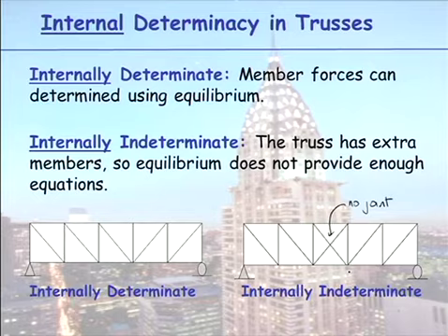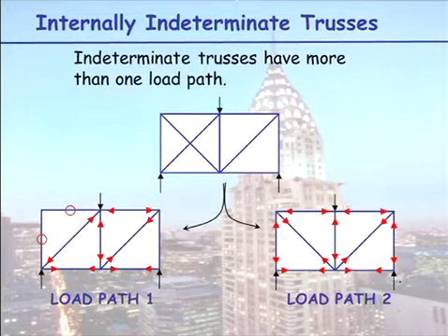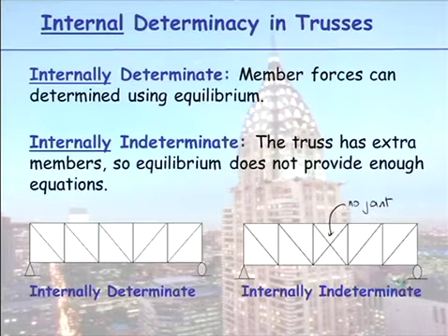Well, we sometimes purposely build in indeterminacy. If you're building something in an area, a war zone, or near transportation, near traffic, on a bridge, where the removal of one member will cause the whole structure to fall down, that's a problem. So we would put extra members in there. So do you scratch your heads and look at everything? No, there's a formula I'll show you in a minute.